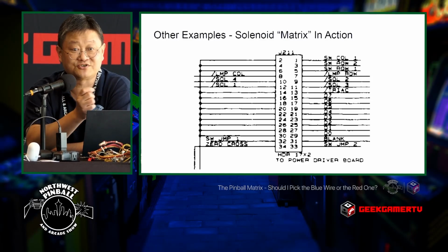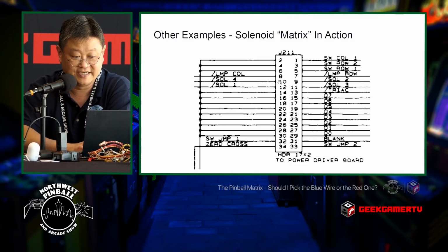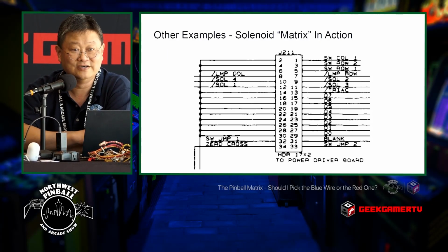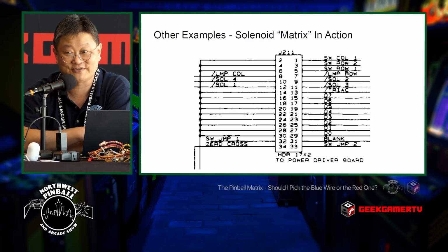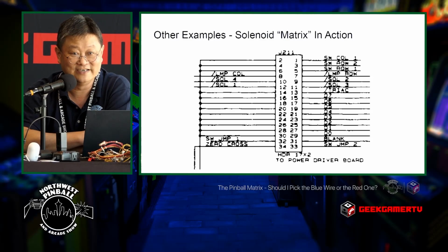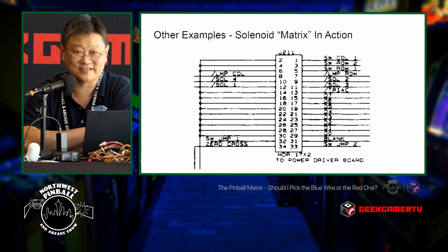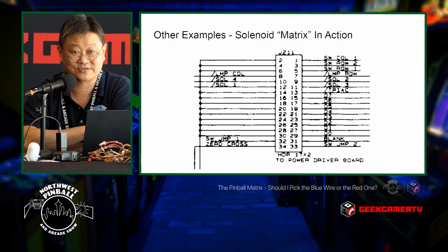And that's how you can see that failure. And the same is true for the lamp matrix. If you look at this power driver board header interface here, you'll see there's also lamp row and lamp col. And those same 8 data bits, believe it or not, are used to control the lamp matrix. So if you have bit 5 out, and you have one of these nice little 8x8 LED matrices, you'll see that col 5 doesn't work and row 5 doesn't work. And you'll instantly know that that data bit is out. Again, failures in groups of 8. It's the nature of the way this thing works.